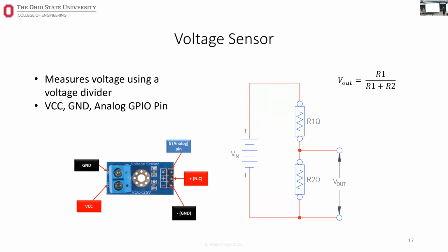So we bought this board already and have prototyped with it. And we get somewhat accurate data, but there's still a voltage offset that we haven't been able to figure out. So we took it upon ourselves to just make our own voltage divider with resistors we had on hand. And we're actually able to get a fairly reliable signal from 0 to 15 volts, which is the operating range of the motors that we're going to use.